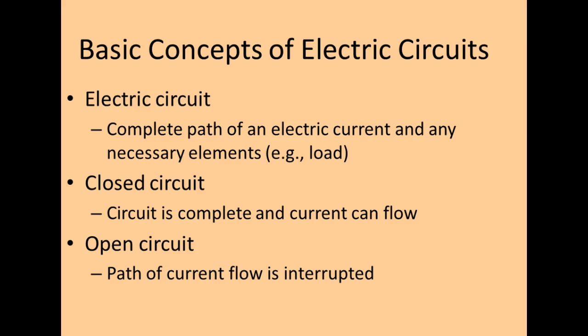Okay? Whereas if I had one, it's getting all of it. If I got two, they're sharing it. And you go, well, how do they always share it? Half? No. Based on their resistance. In other words, if this thing has, say, 500 resistance ohms, and this one has 500 ohms, they're shared equal. Does that make sense? If not, though, it's going to be some percentage.